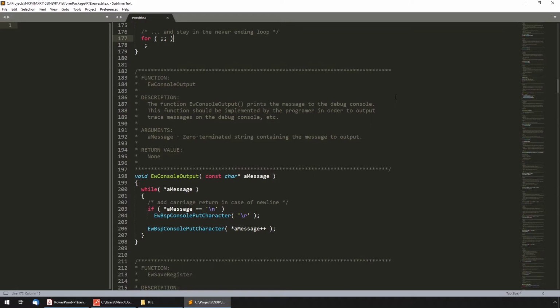Some requirements: when you think about which requirements are essential for Embedded Wizard, in fact, we have 4 requirements. We need a 32-bit system, we need access to the system ticks, we need access to a block of memory, which is then given, for example, to the Embedded Wizard's memory manager as a working space, and finally, we need to transfer the pixels somehow to the frame buffer.